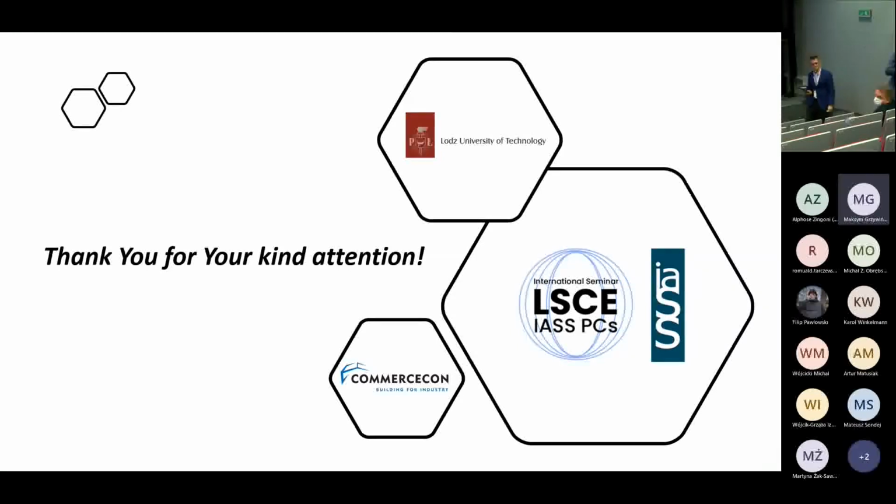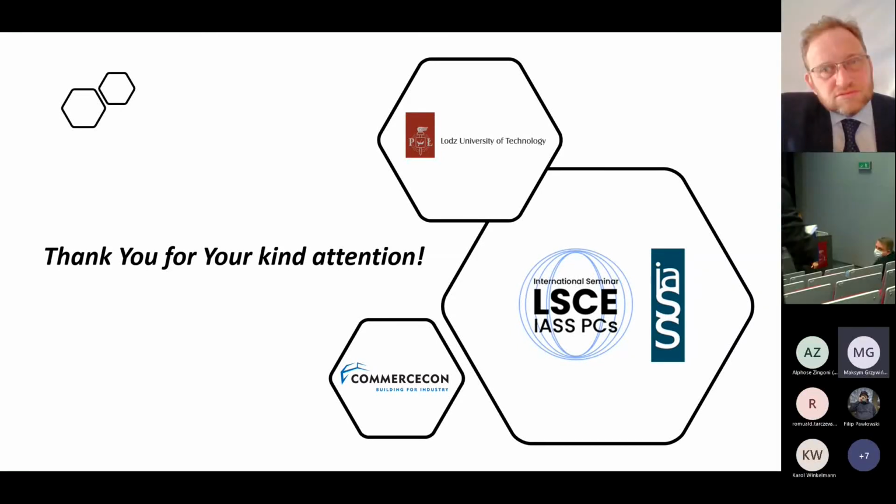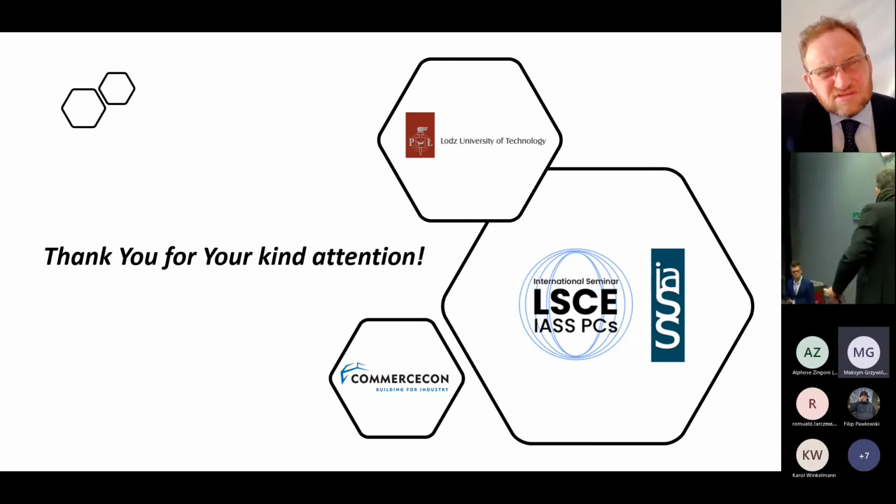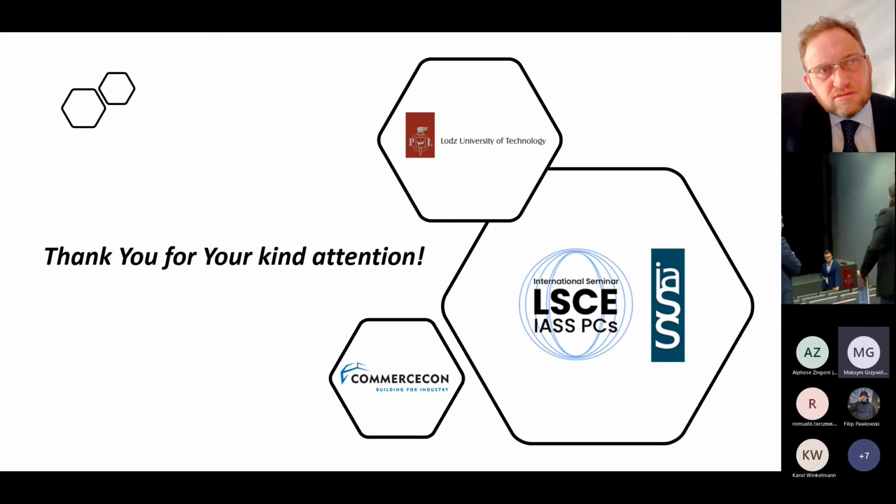Anybody? Yes. I have one question about the natural frequency of the system, because usually when we deal with dynamic analysis, the full transient history of the vibrations of the system, we worry about structures where the natural frequency is less than one hertz. I suspect that in this type of structure, the first natural frequency is much higher. So do you need such a detailed dynamic response in wind excitation?